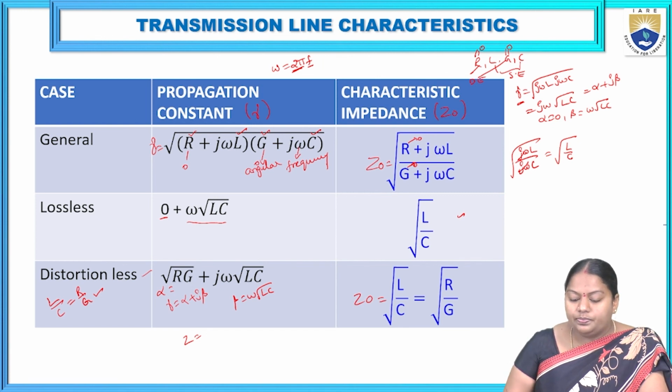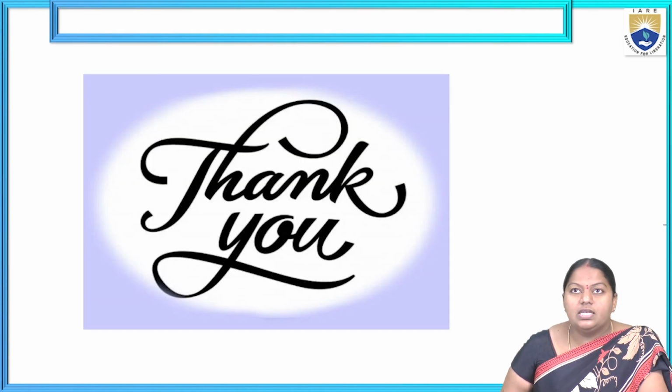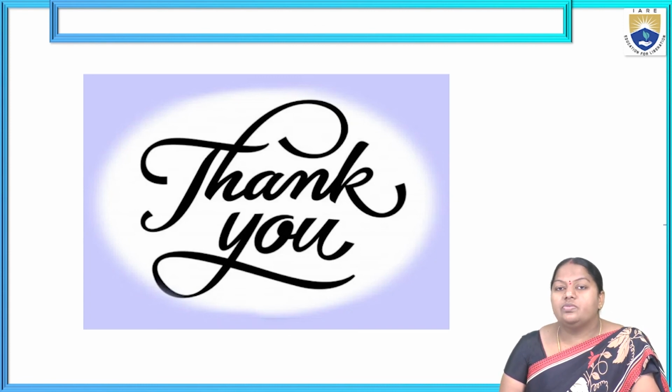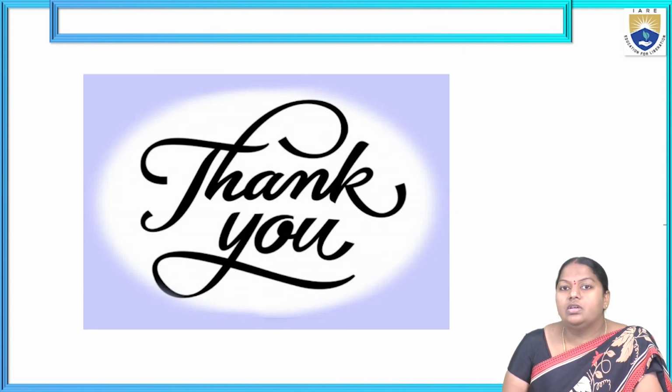So what we have learnt in this particular lecture is, first, the minimum condition for attenuation. To evaluate that, we considered the attenuation constant alpha, and to derive the condition it must satisfy the simple condition d alpha by dl equal to 0.